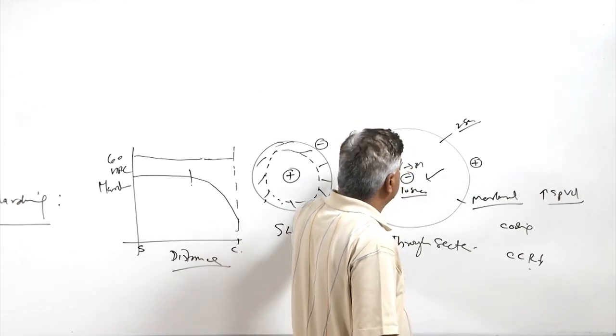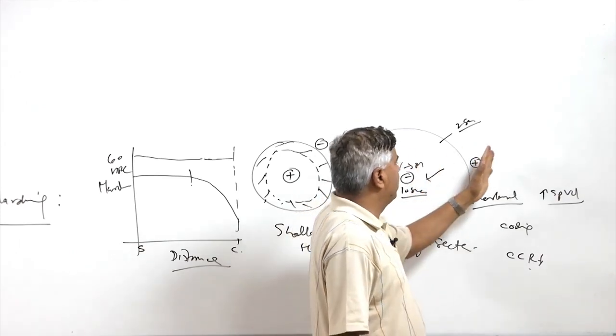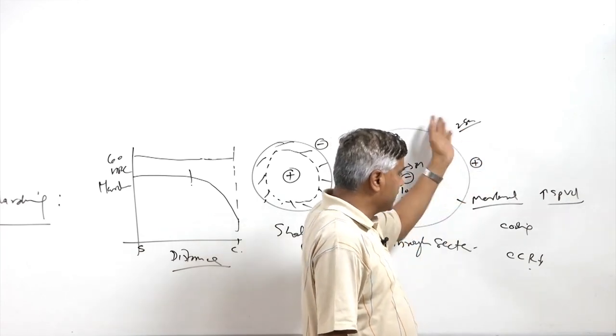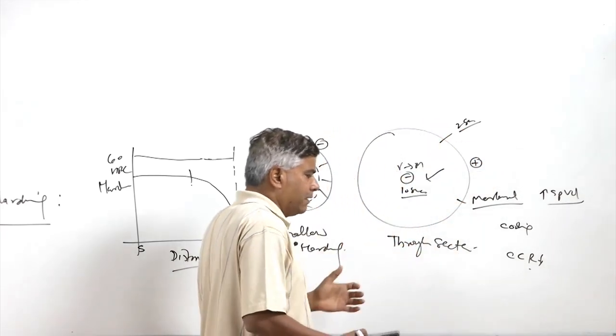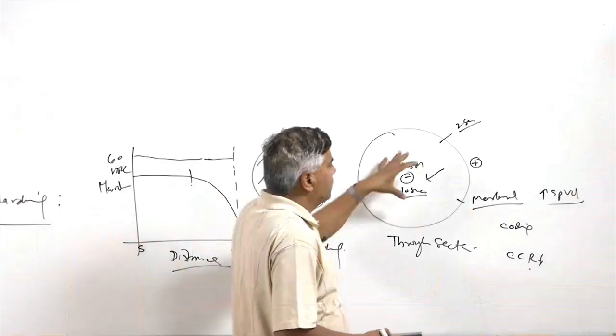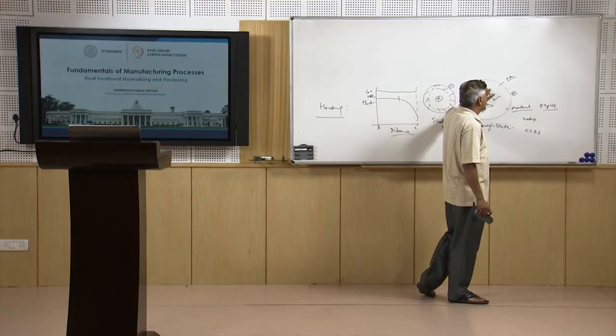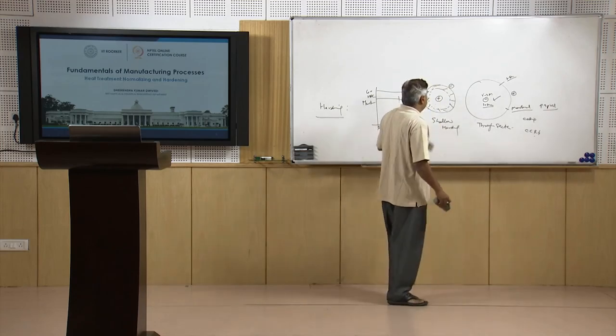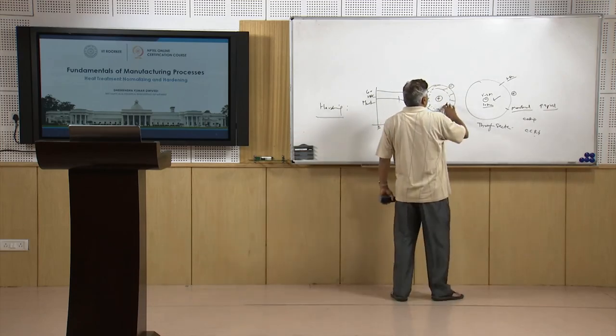This increase in specific volume causes the development of tensile residual stresses at the surface, because the surface cannot relieve the strain caused by the increase in specific volume at the center, since it is hard and brittle. In the other case, just the reverse happens.